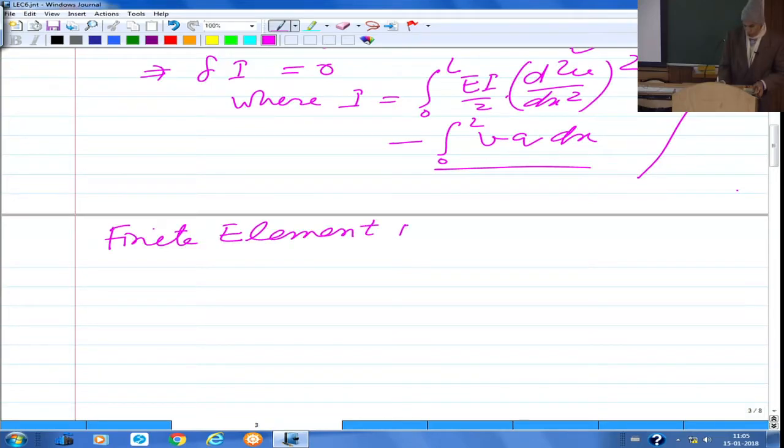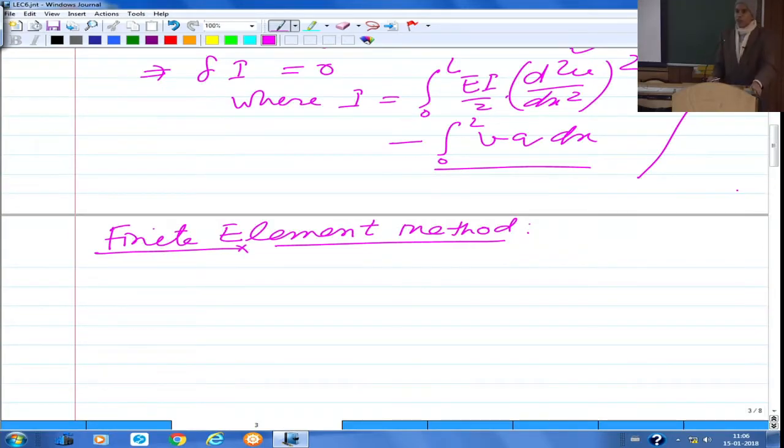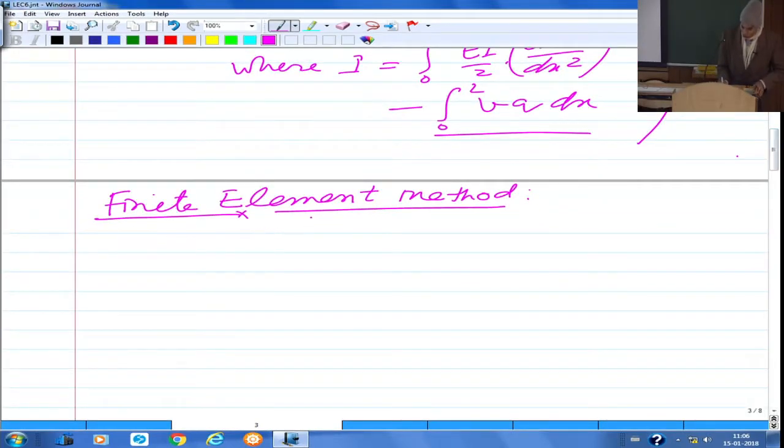So far whatever we have done is just the basics which are required for this. So I am going to, as the name suggests, finite element. So you have an entire domain, and finding an approximate solution which is valid over the entire domain is again usually a difficult task, or you get simpler solutions which are highly inaccurate. So you try dividing the domain into smaller subdomains, and then you are looking for a piecewise continuous solution. This is piecewise continuous approximation, let me say.